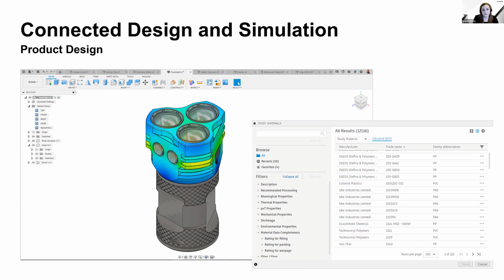When we finalize the assembly design, we can run through a quick thermal steady state analysis, which is shown here on the screen, with the materials assigned and the heat sources specified in order to show that heat source there. Now, this allows us to evaluate the safety and integrity of that part individually.